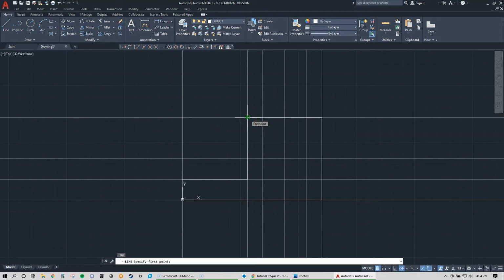Now let's put the ribbon. That starts from up here down to here. If you're not getting these little green indicators when you're trying to click little spots, make sure your object snap is on down here. You can also turn that on with F3 on your keyboard.